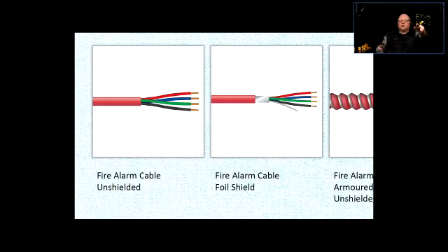The FT4 and FT6 standards have to do with fire conditions. FT6 doesn't burn as quickly; anything can burn if you get enough temperature, but FT6 is considered more fire retardant, or fire resistant. That means it's still going to burn, but much later than FT4.